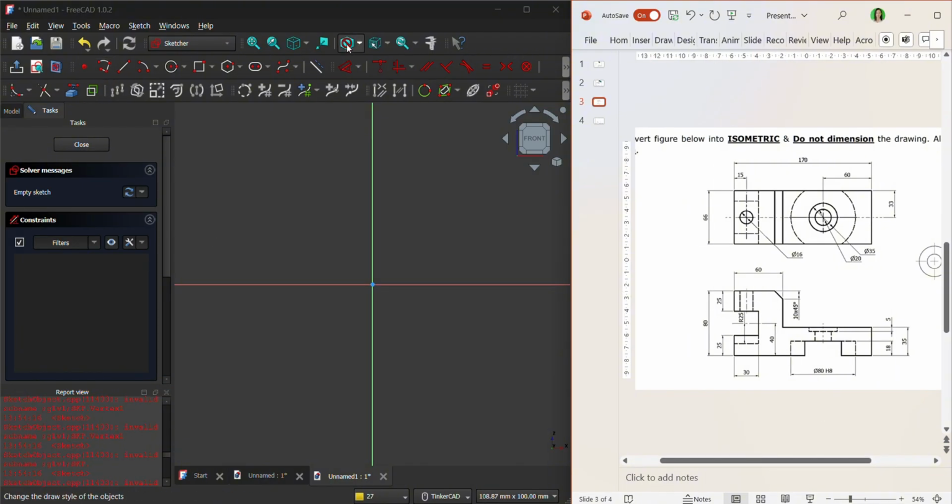The first tool that we are going to use is called Polyline. You will see the name if you hover your mouse on the tool, but this time it's not showing here, but here it will appear at the bottom left corner. It's Polyline in the sketch. You can also use the M key. I think it's the shortcut, but I prefer using this. Okay, so let's start drawing here.